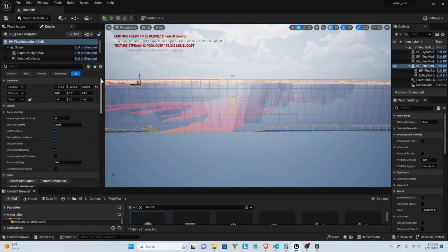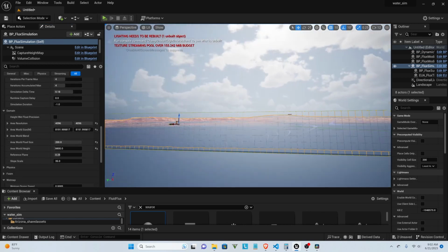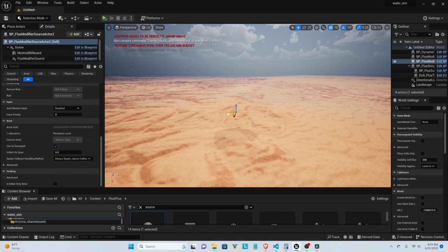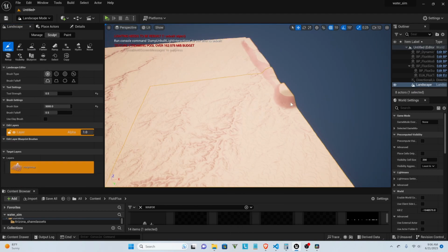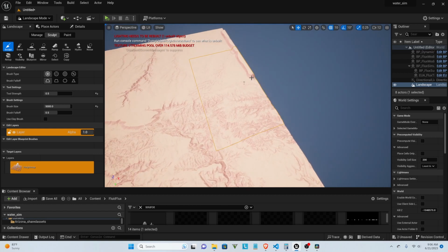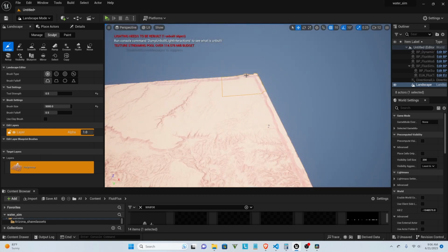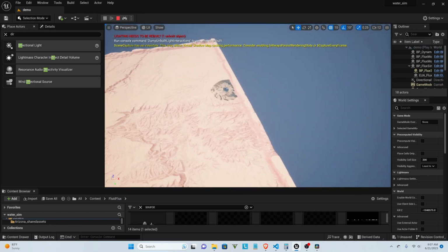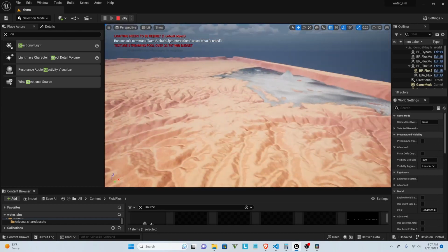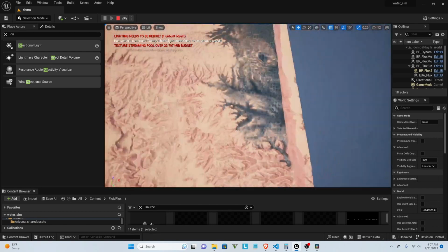Now, in this case, it didn't work because my highest point wasn't above the actual highest point of my map, which resulted in water spawning underneath the landscape terrain, and the landscape was unable to catch it, resulting in water spreading on the floor. For this case, I needed to raise the edges of my map to prevent the water from flowing over the sides, but this probably wouldn't have needed to be done if the water simulation size did not actually exceed the edges of the landscape.